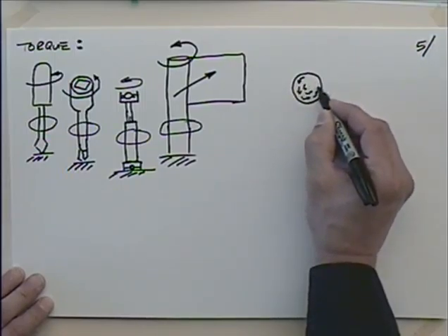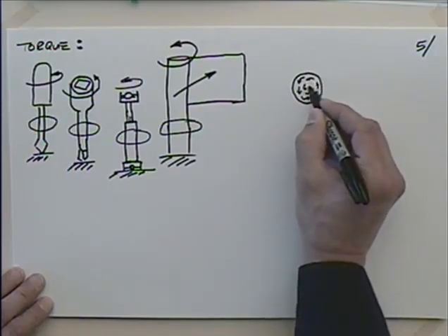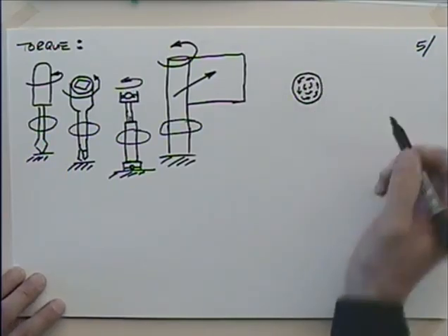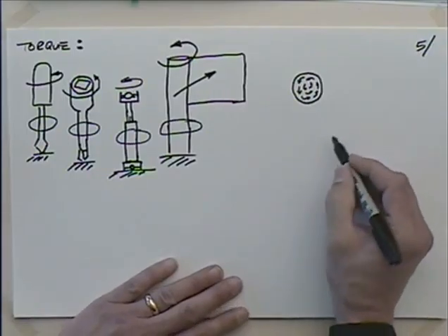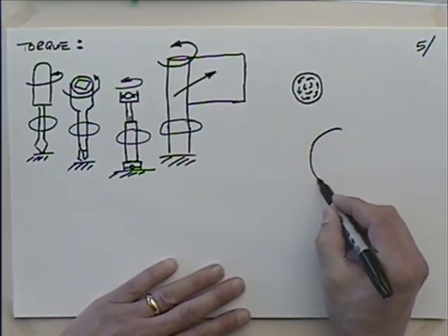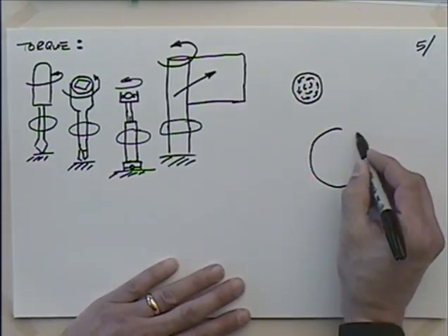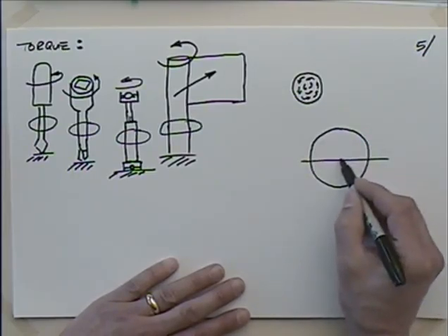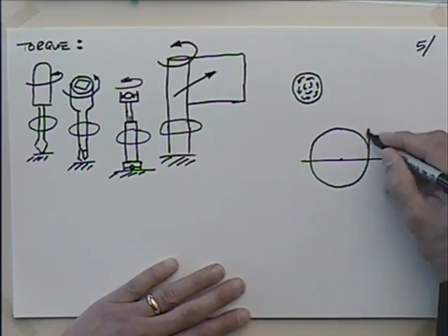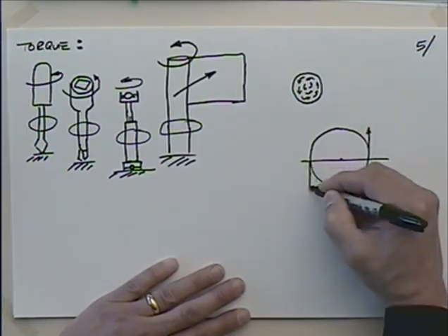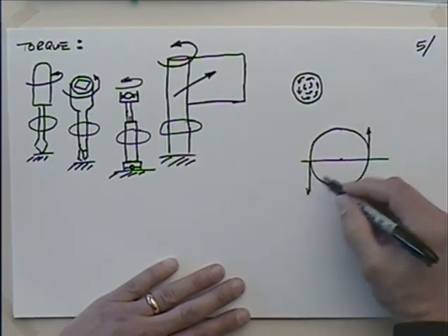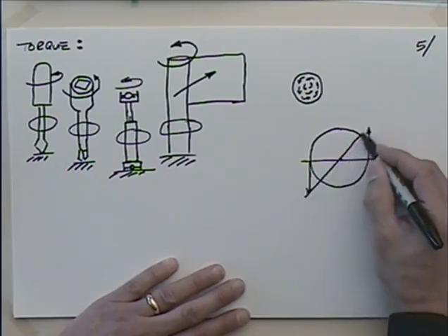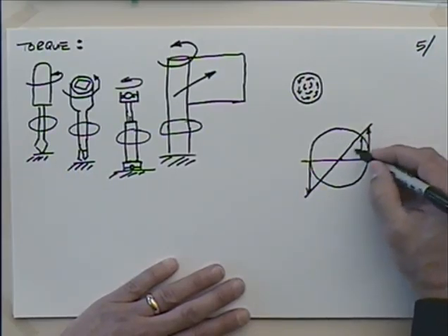Okay, probably not uniformly, but it would be carried across the entire surface. And if I were to quantify that a little bit, let me draw this a little larger. And I could talk about these stresses. I could say that I'm going to have probably the largest stress at the extreme edges. And then it's actually going to be linear across the cross section.